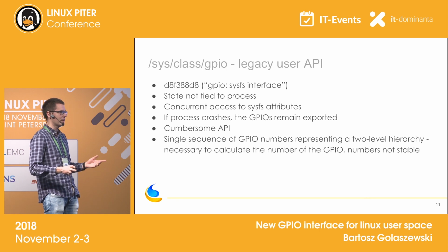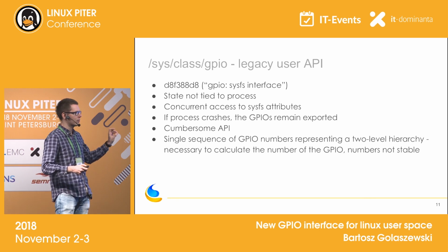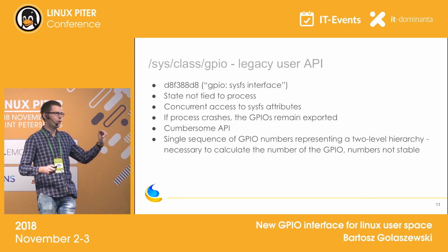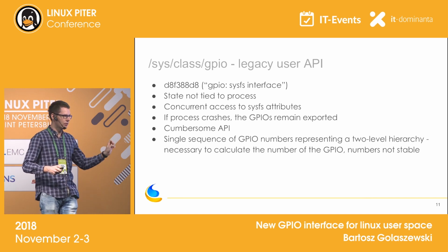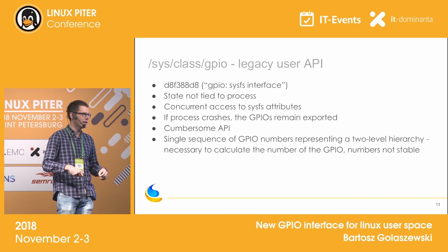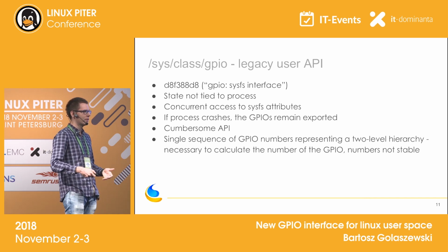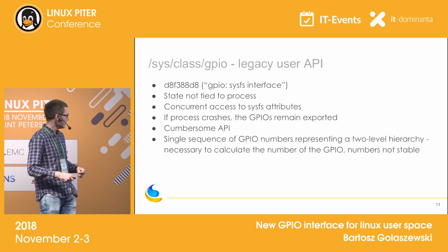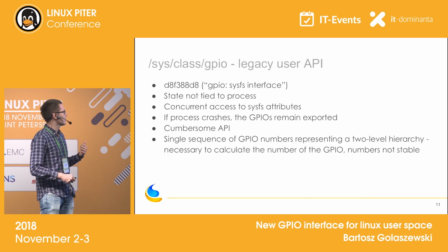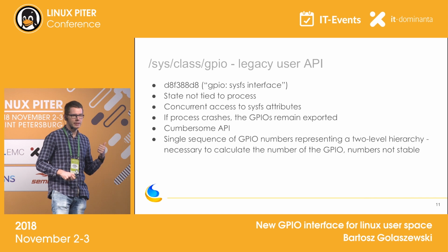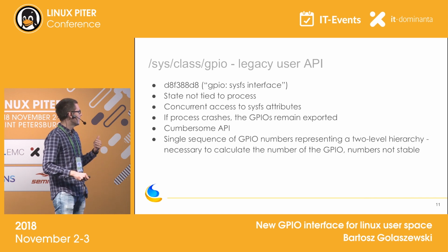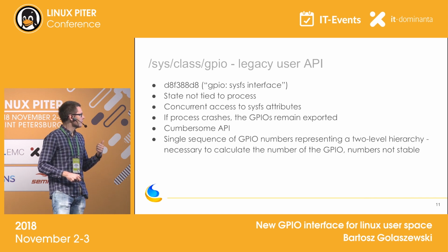Because sysfs is actually, so this framework, yeah, this is interesting. This framework is actually the user of the old legacy number space based kernel API. If you look into the code, it actually does that. It exports the GPIOs using the old functions. Next thing is that we can have processes concurrently accessing the GPIOs and getting in each other's way.